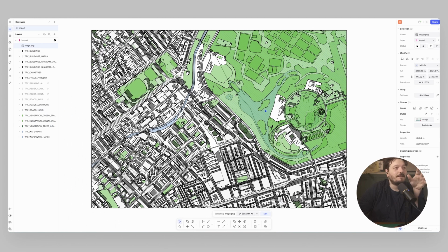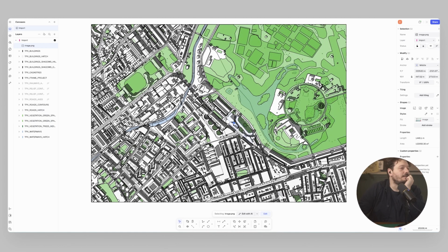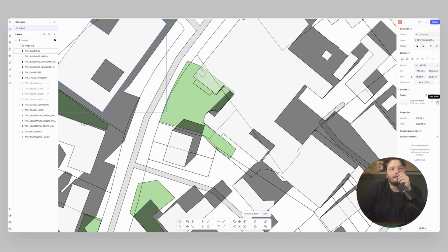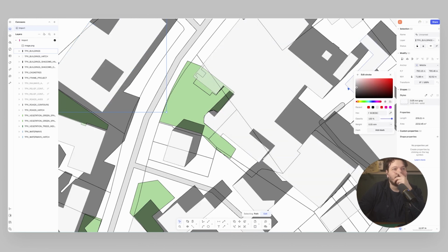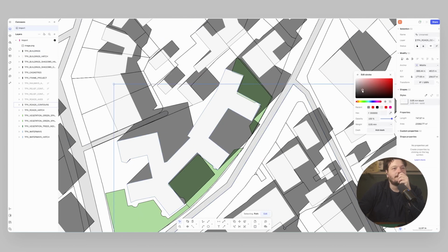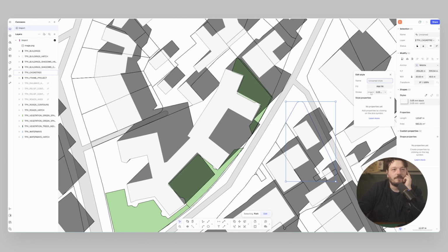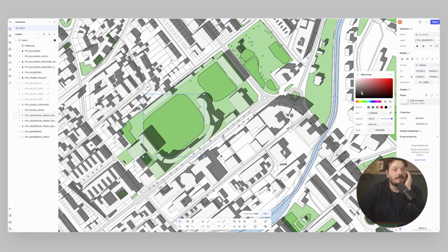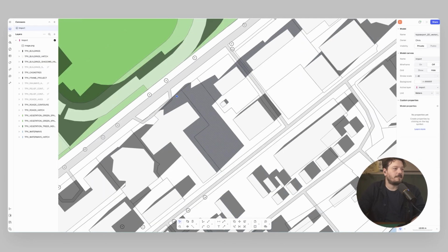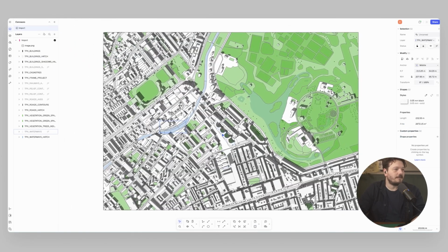So now we've understood the layers, we can go in and we can edit things. So say for example I wanted to change the tone of this drawing, so how it appears. So I could try and find the line weights, for example. So you can see my styles have been set up here. I can go into these styles and I can say, maybe I want something a bit lighter in tone to the line work. Same thing with these styles, so it's not quite as harsh. And ultimately, because I'm changing the style, it's changing all of those elements that are pasted with that style, for example. I could start turning layers off. Yeah, it's already starting to look a bit softer.